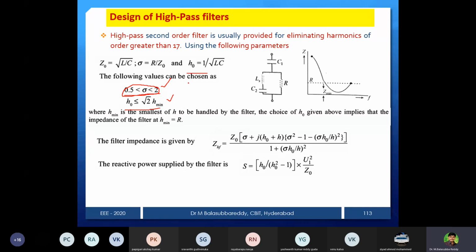What you will do is take a transmission line from the source, and then some transmission line of 10 kilometers or some impedance you can take, and on the load side you connect some reactive power, some inductance and then capacitance. And now you just connect a power meter. There is one voltage input, and current is another input. You see what the real power and reactive power are. In the same way, on the load side you also measure the load voltage and then the load current. Connect one power meter for reactive power and real power. In the simulation, a power meter block is there.